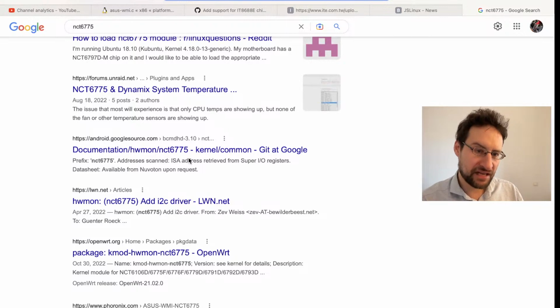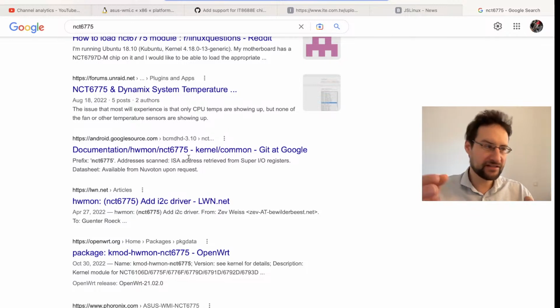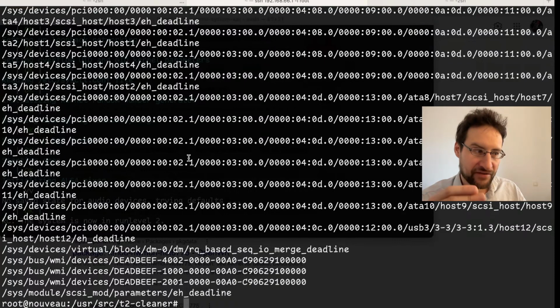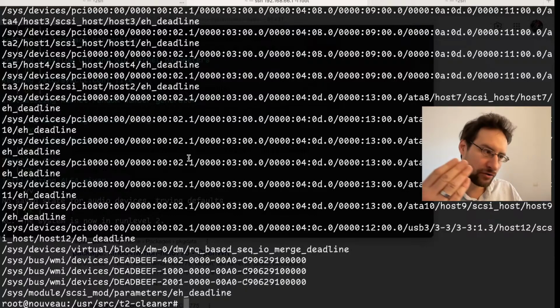It could be that that other driver only works with a motherboard that might be using an NCT 97 whatever chip, because obviously the motherboard vendors alternate, depending on the supply chain, like what they get in quantities or cheaper or whatever. So other motherboards are using other Super IO or temperature sensor integrated circuits. While this API looks quite generic, so this GUID is there, it doesn't work the way the Linux kernel driver is written for me. I could reverse engineer that another day, but I'm not reverse engineering and disassembling the BIOS right now.